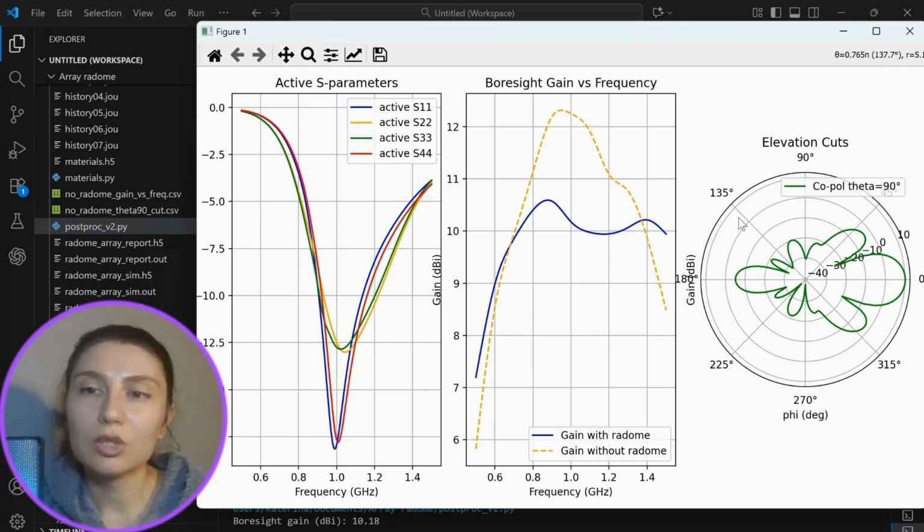And when it comes to the radiation pattern itself, I wouldn't expect any changes here. Usually, when we don't design an electric lens specifically or something, we don't want this effect. We usually want the radome to be a very transparent structure for the antenna, as transparent as possible, if we don't want any specific properties from it.